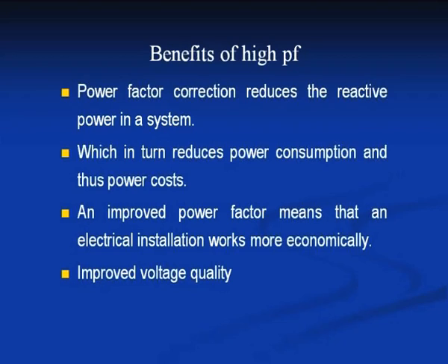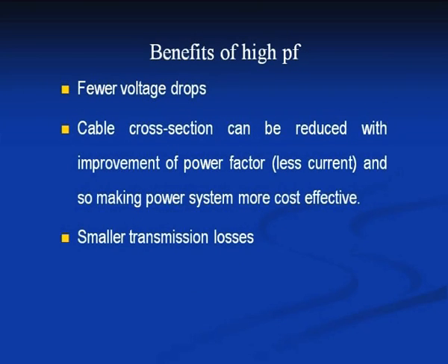An improved power factor means an electrical installation works more economically, and a high power factor also leads to improved voltage quality, fewer voltage drops, and the cable cross section required for delivering the power is also reduced with the improvement of the power factor, which in turn makes the power system more cost effective. And high power factor also reduces the transmission losses.